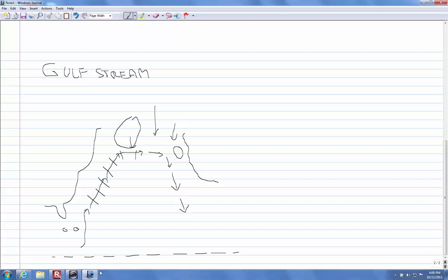And once again, now we need to look at the expected size of the rotors, how big we think they're going to be, and then we go back to figure 629 and say, okay, where's the water moving at? So I either need them outside of the shipping channels or isolated in a way that there's no way a ship could run over them, or I'm going to capture less energy because they have to be down below the surface of the water. So it's a trade-off, and it's definitely something that you have to look at.